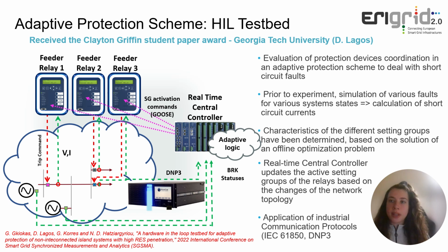This hardware-in-the-loop testbed was designed to evaluate the protection devices' coordination in an adaptive protection scheme to deal with short-circuit faults. Prior to the actual implementation of the experiment, simulations of various faults have taken place for various system states to calculate the short-circuit currents. According to the observed results, the characteristics of different setting groups have been determined based on the solution of an offline optimization problem, and the different island states were grouped into 4 conditions.